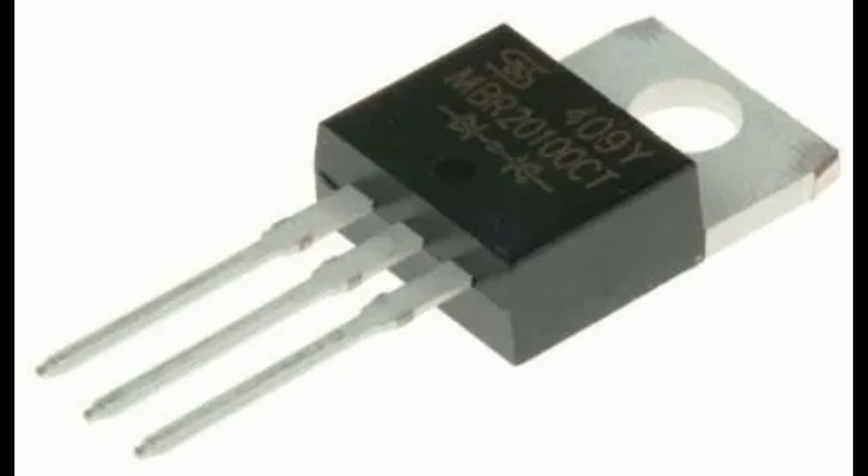Junction capacitance can have significant effects in electronic circuits, especially at high frequencies, and it is desirable to keep it as low as possible for several reasons. High-frequency performance. In high-frequency circuits, junction capacitance can limit the speed and performance of the device. Low junction capacitance allows for faster switching and signal processing, enabling high-frequency operation.